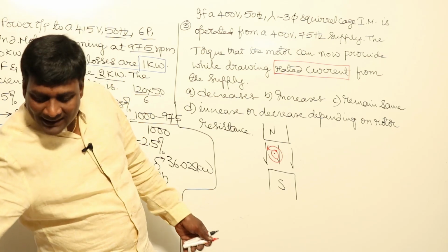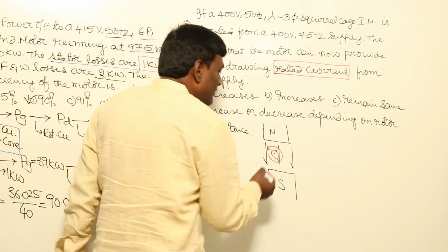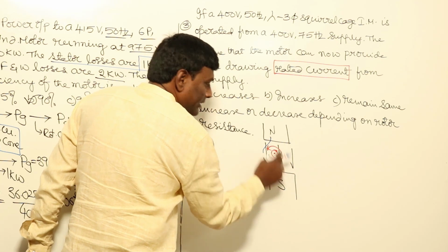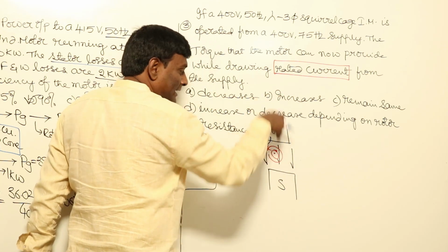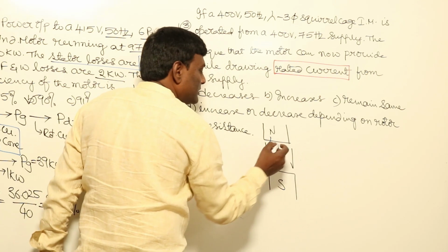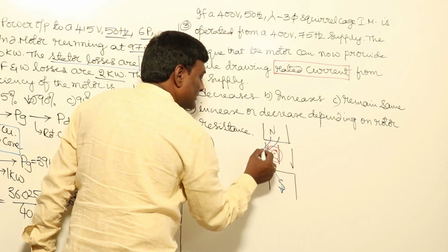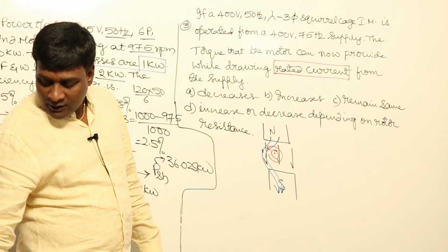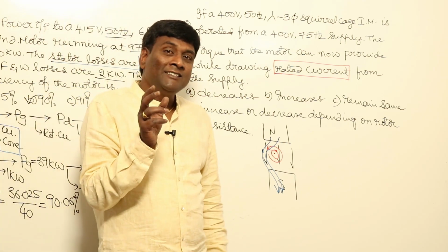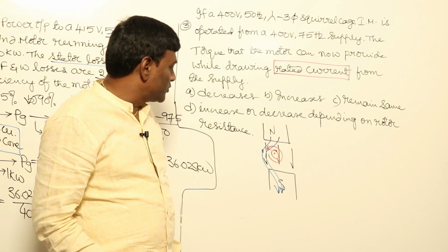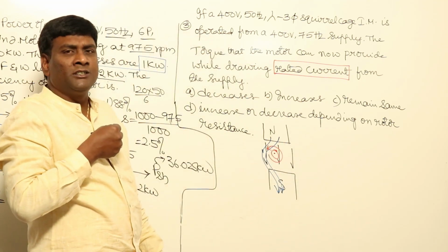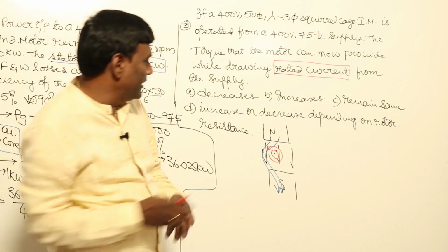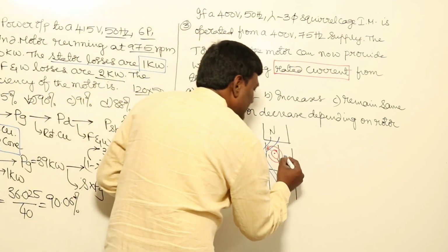The net resultant of these two is going to be aiding and opposing. For example, one flux line is flowing in this direction, the red is flowing in the opposite direction, so all fluxes will come like this. As I told previously, my flux lines will behave like a stretched rubber band. So all these flux lines are stretched. If I release, torque will be developed in this direction.